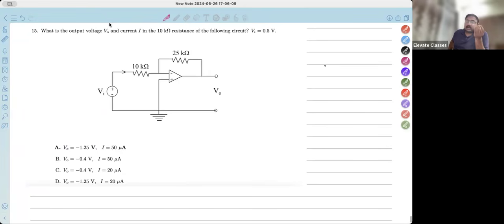We have solved all the PYQs, almost all PYQ. I think ये एक बच गया था. TIFR में भी कोई PYQ नहीं था दिसंबर के. Otherwise, we have solved every single PYQ on op-amp almost. Okay. So op-amps is again a very scoring topic. Go through it once. Negative feedback है. Op-amp is in linear region. Virtual ground concept is valid. That's all. Let's check. Is there negative feedback? Output is connected to inverting terminal.